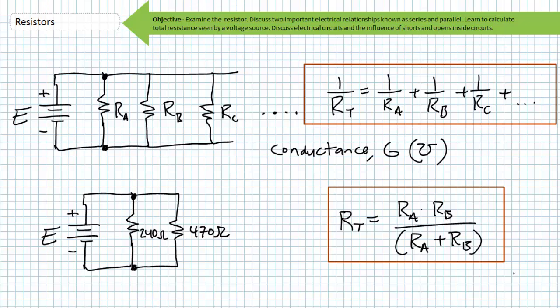How much less? It should be always less than the smallest resistor because there are now two paths in parallel. If you get any value higher than 240 ohms, you're doing it wrong. It helps to have some boundaries before you bound off into the woods. Let's put our final answer in the most appropriate engineering prefix and go down to the 10th place. Use whichever formula you wish.